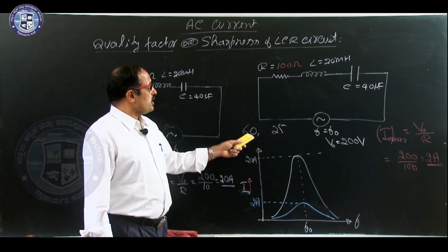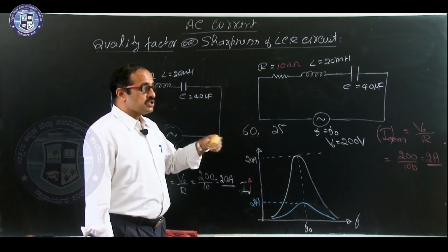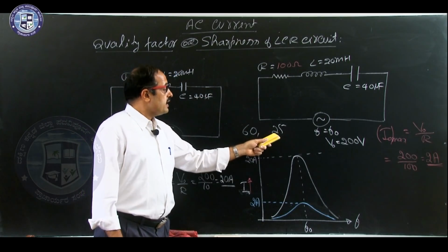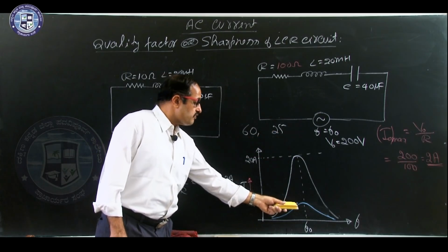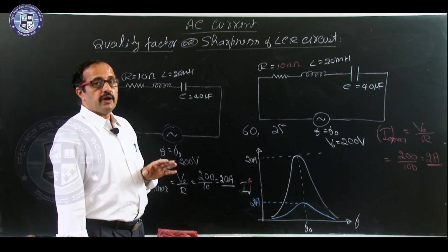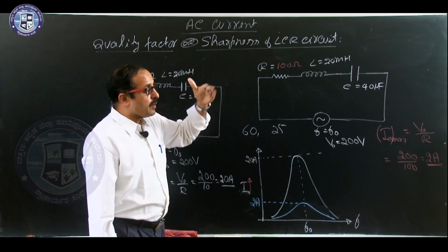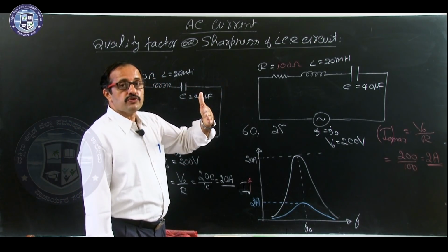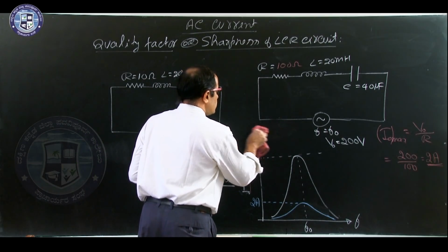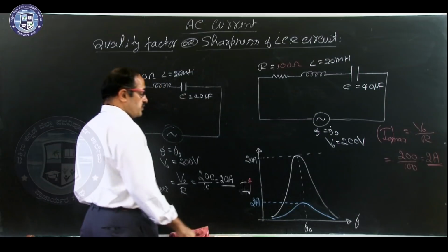Then immediately we come to know quality factor 60 means you have to recall this graph. In this circuit current sharply increases and curve is more steep, and here it is 25 where graph is almost flattened, remember. Current changes with the frequency, but the changes are negligible, difficult to notice, but in this case current rapidly changes when you approach the resonant frequency. So, quality factor tells to what extent current changes with frequency, especially nearer to resonance.